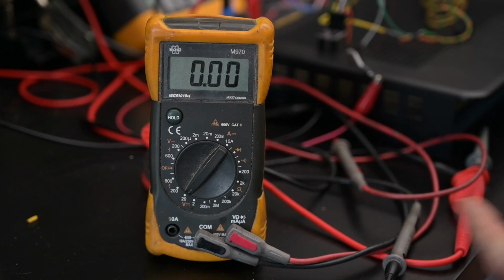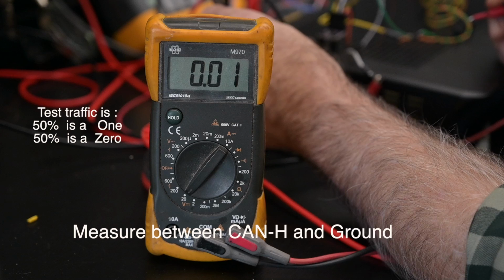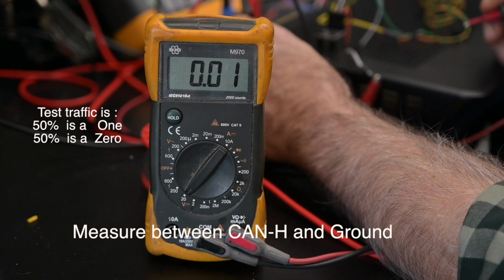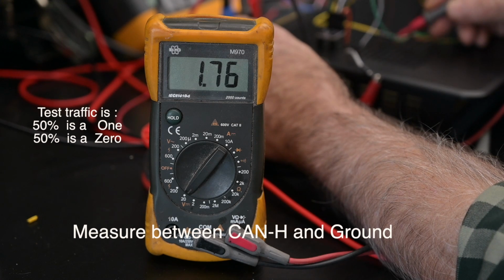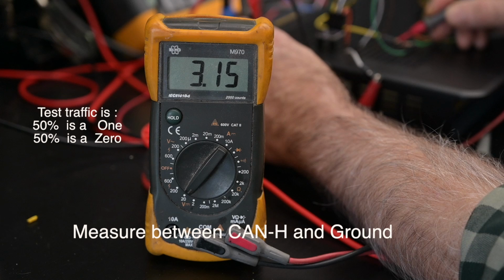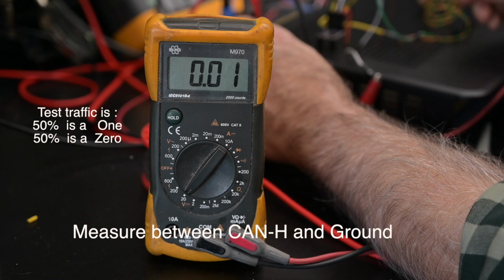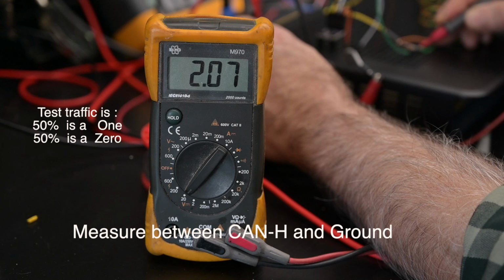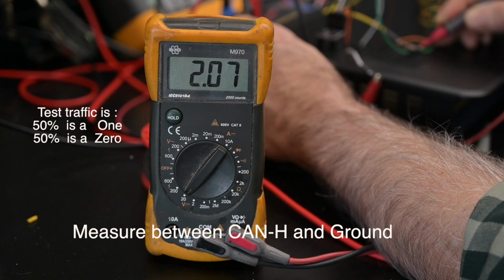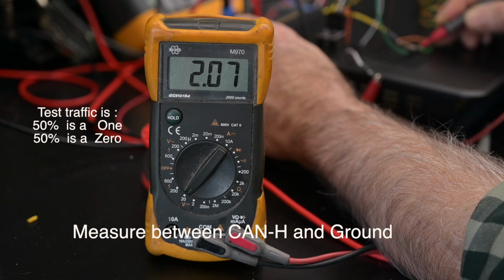So I've set up the voltmeter to a DC scale, and I'm going to measure the CAN high first. And we have some traffic on the CAN bus. And let's see what it gives us. I think what we measure is about 3.1 volts, and that's about right because the signal is toggling between 2.5 and 3.5. And then the CAN low is about 2 volts, and this is going to toggle between 2.5 and 1.5. So all depending on the pattern of the bits on the line, you may see different values.